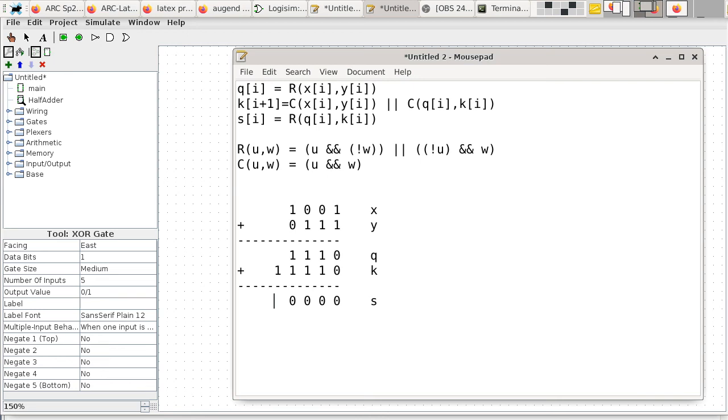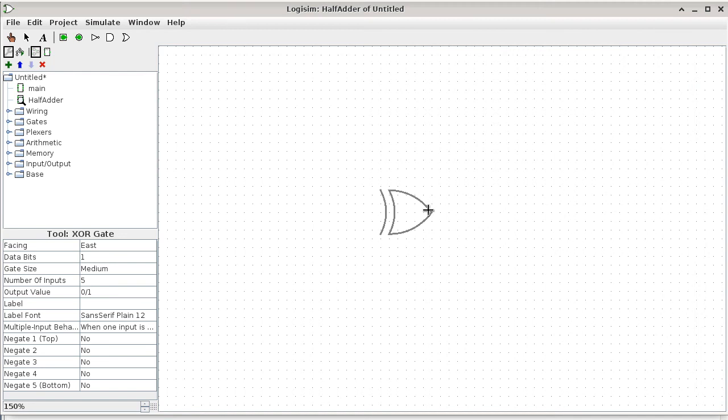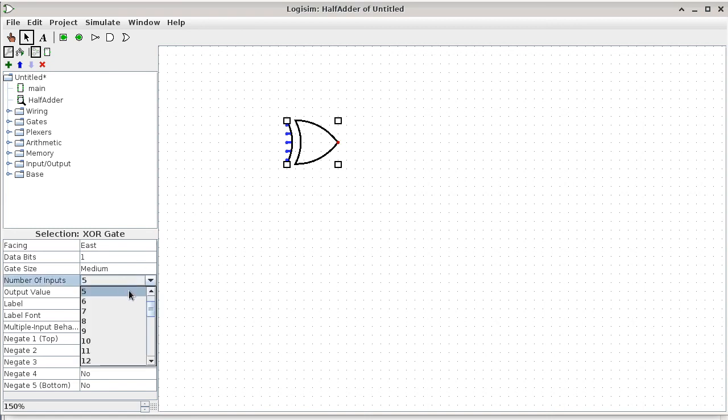The half adder circuit really doesn't have much to do. It has to do the exclusive OR, and then it has to come up with a potential carry bit when we add these 2 bits. So it has to compute the R and the C, the carry, and that's it. We'll go ahead and build that circuit in LogicSim. I'm going to cheat a little bit and use an exclusive OR gate instead of that complicated version of exclusive OR, so the circuit looks nicer.